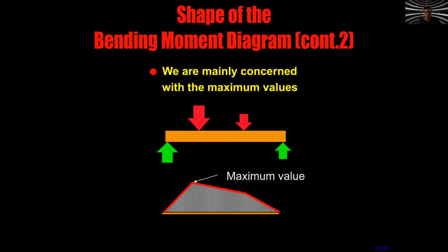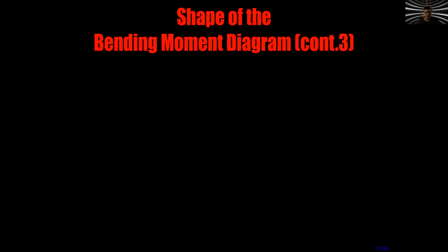Well, we have shapes of the beams, and the most important thing is that we have maximum values. The maximum value is fundamental because if we know the maximum shear and the maximum moment, then we can calculate what type of beam we will need. We can go to Home Depot, get a table and say, well, I want a piece of wood, let me look which one I need. This particular piece of wood has a maximum moment, a maximum shear that it will resist, and then you can choose that one.